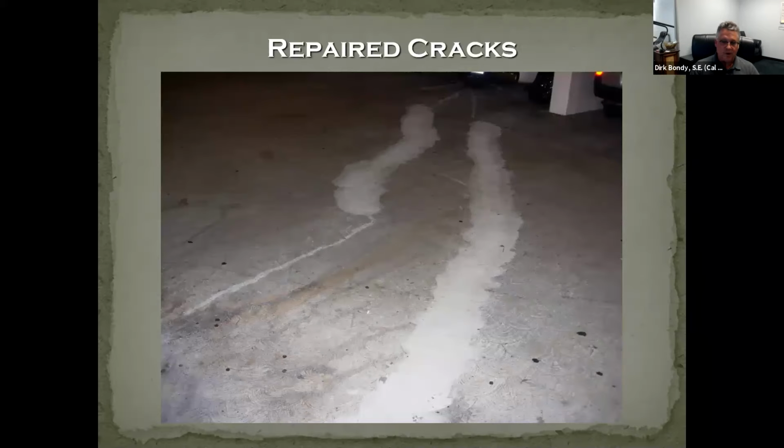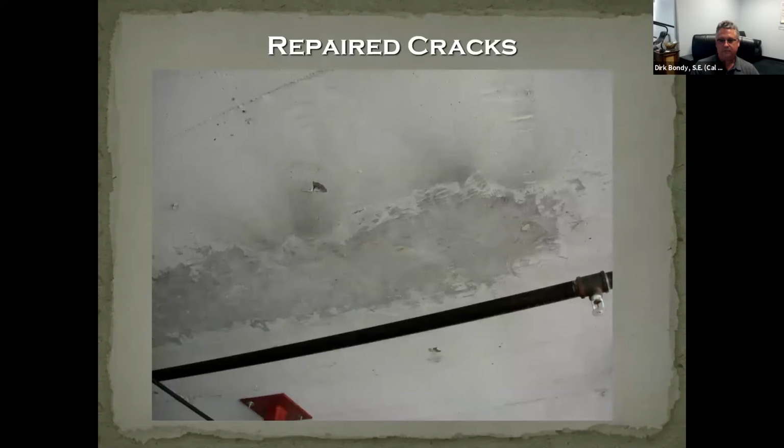This is what repaired concrete on our project has looked like. It's not particularly pretty, but the moisture intrusion and the cracks have been arrested. This is one of those large sections that had fallen from the slab soffit. Again, not particularly pretty, but Sika, at least in the United States, provides very good products that can be used for repairing and patching concrete. Very high density, tight concrete, high strength. That's what you want. You don't want even air getting in.